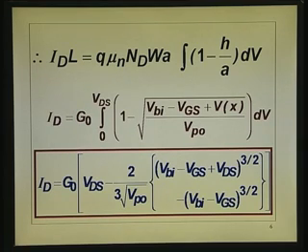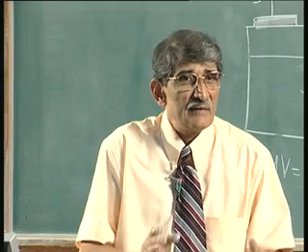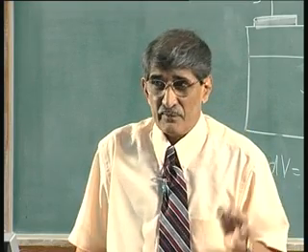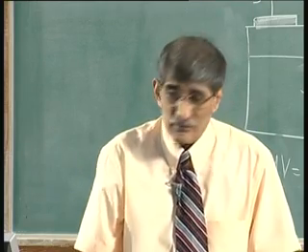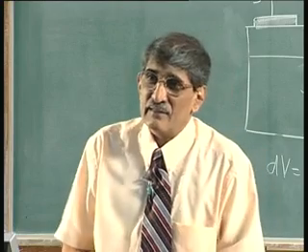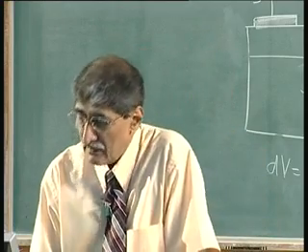Let us see that. When V_bi minus V_gs is large compared to V_ds, that is V_ds is small, that case we have obtained from first principles in the previous lecture by taking the width to be constant. Now, this must hold good, and we have to get back that equation if what we are saying is correct. Let us see that.